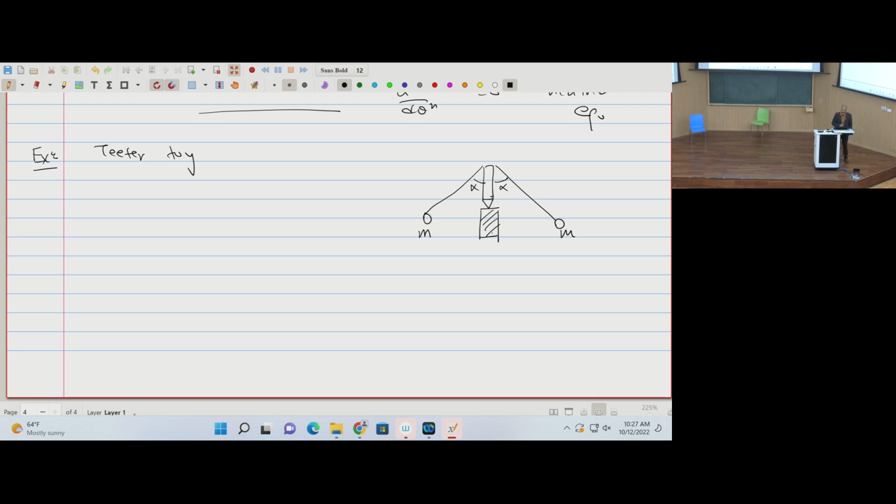Now what happens is, I ask you this question, well, this is supposed to be symmetric, it looks slightly asymmetric, better. So I ask you, check if the system is in a stable equilibrium. What will you do? You will calculate the potential energy function, let's say as a function of theta. So you take this and you give it a displacement.